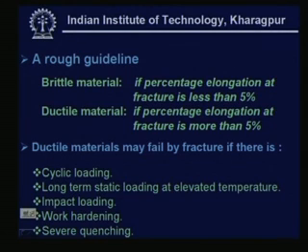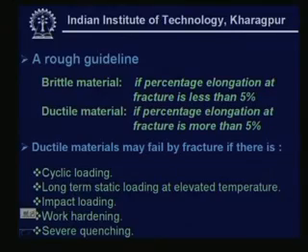Just due to that particular temperature effect, what happens? The simple mild steel, which was behaving like a ductile material, may just behave like a brittle material and fail. These sorts of incidents had occurred in World War II, when ships from the German side went to the Arctic ocean sites. So the effect of temperature, combined with impact, is also a severe situation where brittle failure behavior can be exhibited in a ductile material too.